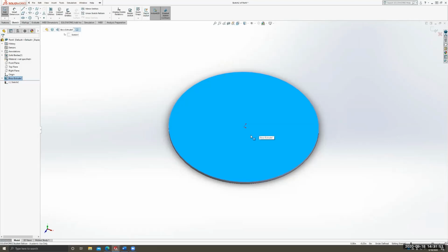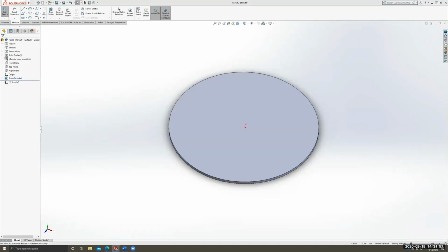So as soon as I click that, how do I fillet this edge? Do I have to click the edge if I want to fillet it? Yes, you can click the edge to fillet. Sometimes there are parts of a face that can't be filleted, or the radius of your fillet is too large. If you click a face and no fillets come up, try decreasing your radius and it should show up. Okay, I just got it. Thank you. You're welcome.